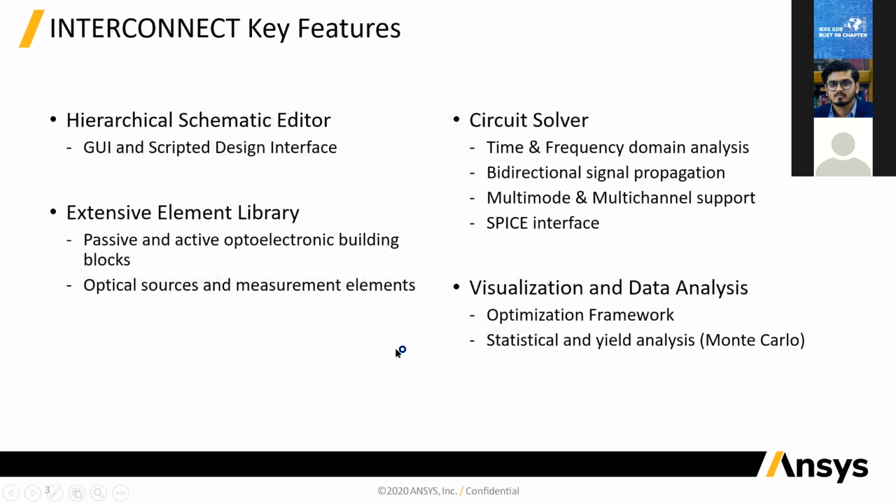So here are some of the key features of interconnect. It's a circuit solver, so it uses a hierarchical schematic editor. You can create your circuit and you can have different levels. For a huge circuit, you can break it down into different compound blocks and then go inside the blocks and define sub-circuits. That way you can keep hierarchy in your design and keep things cleaner.